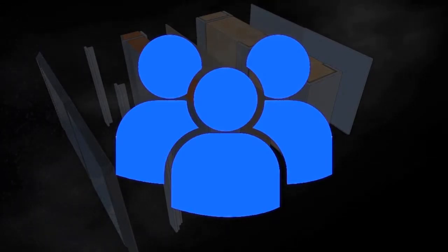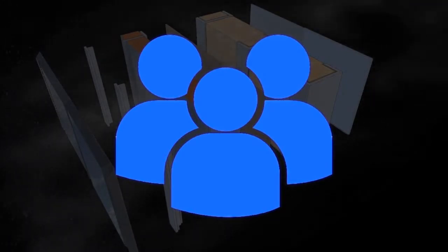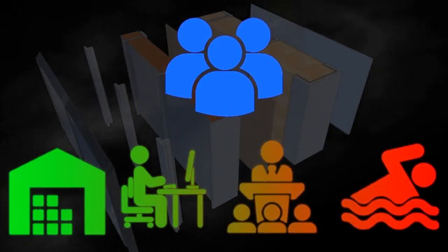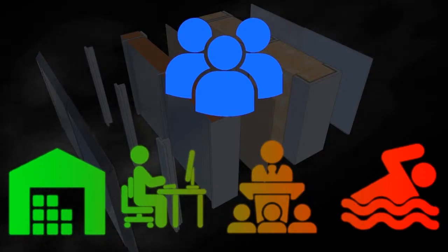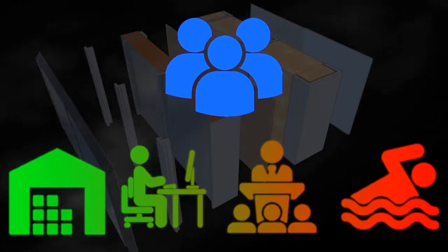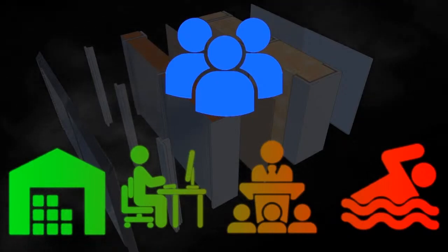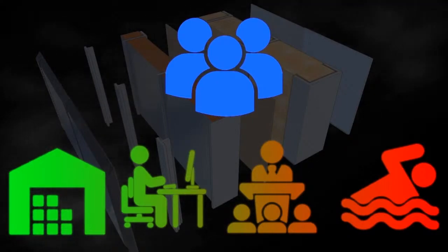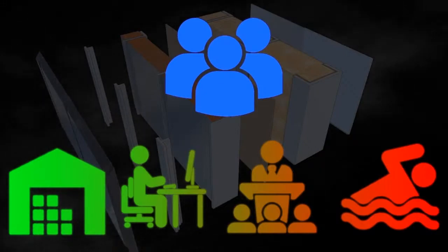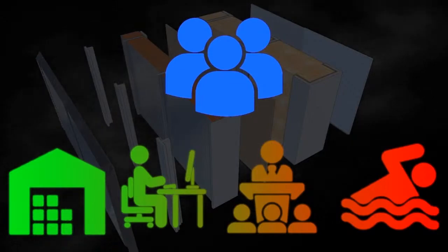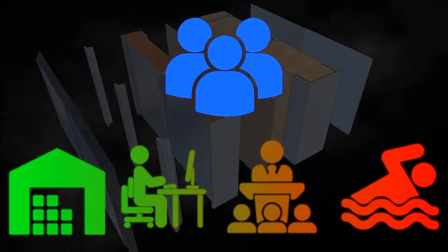Internal moisture sources must also be considered. Achieving an effective and efficient moisture strategy depends on the design being carefully matched to the building's function. The same design that works for an office may not work well in a sports centre, for example, at least not without significant over-engineering and added costs. Developing a thorough understanding of both how the building as a whole and specific areas within the building will be utilised by its occupants and the corresponding moisture production is key to achieving a robust and cost-effective design.